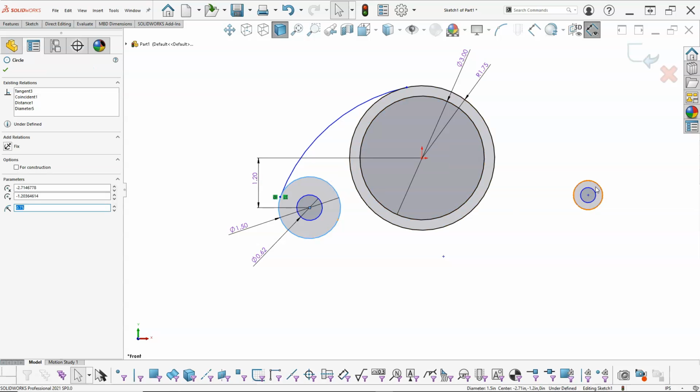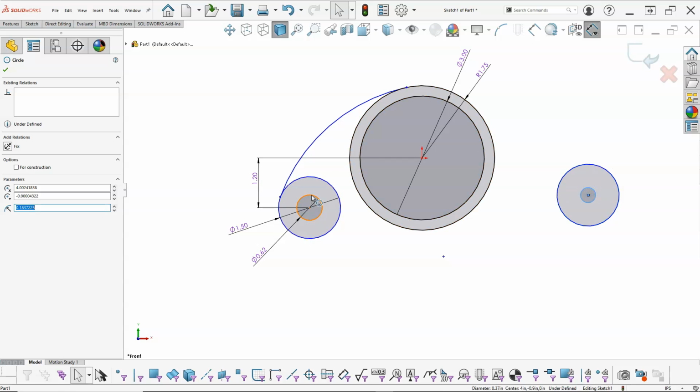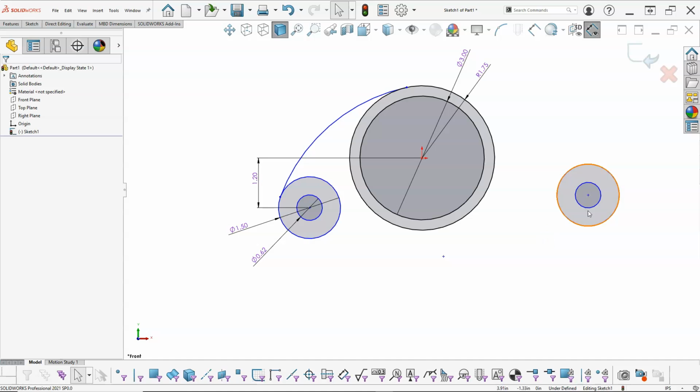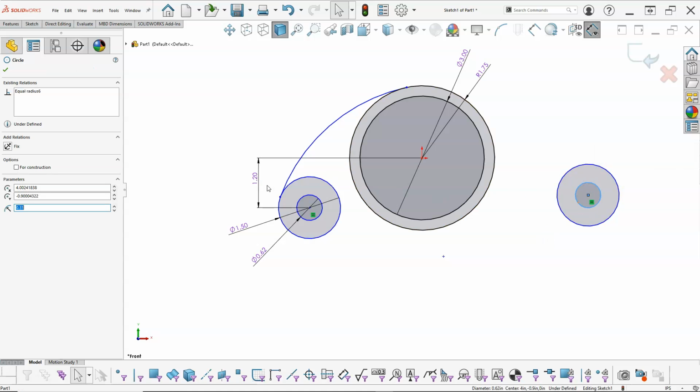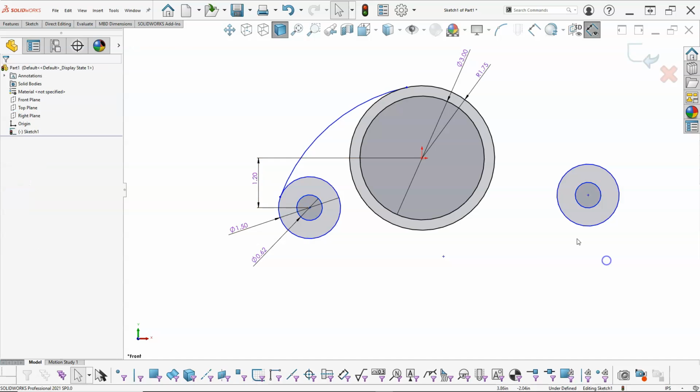All right, so since these are the same, rather than putting dimensions, my design intent will probably be that they're going to stay equal, and that's easy enough to identify. So select, Control Select, set to equal, and that pop-up is going to be faster, easier than setting it and always coming over to the left. Occasionally we're doing multiples. We'll apply the first one and then come over and do the second.